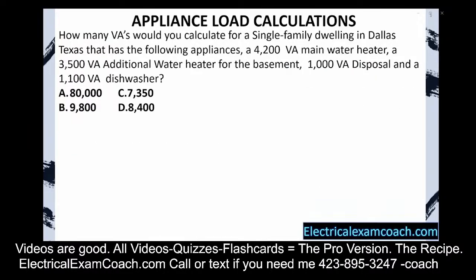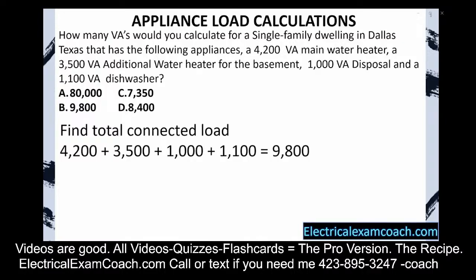How many VAs would you calculate for a single family dwelling in Dallas, Texas that has the following appliances: a 4,200 VA main water heater, a 3,500 VA additional water heater for the basement, a 1,000 VA disposal, and an 1,100 VA dishwasher? First, we're going to find our total connected load. We take and total it up, and it equals 9,800. Now, we check for demand factors.